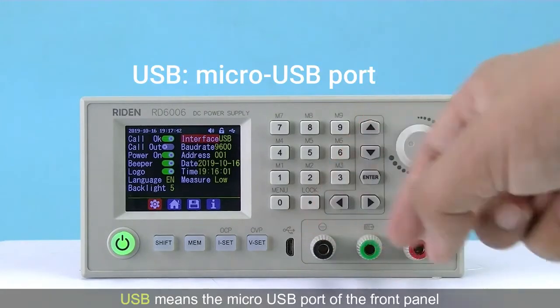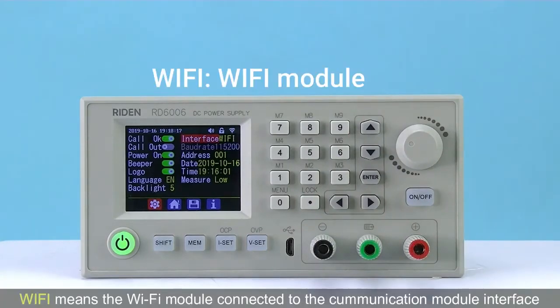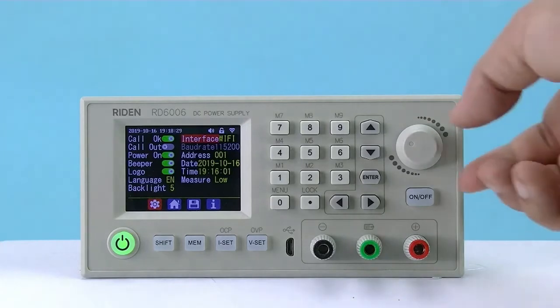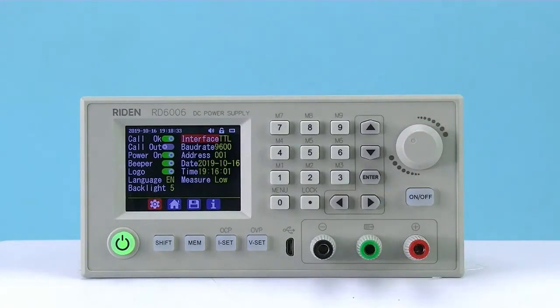USB means the micro USB port of the front panel. Wi-Fi means the Wi-Fi mode connects to the communication interface. Use Wi-Fi to connect RD6006 and the mobile phone app. You need to choose the Wi-Fi mode. TTL is not available now.